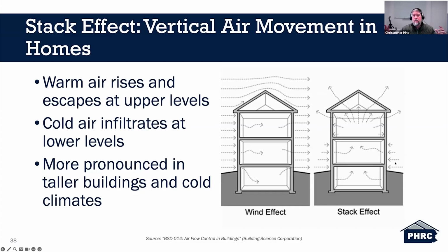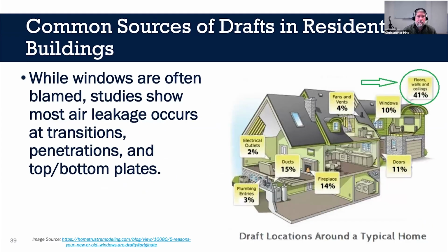Again, because you are creating a depressurization at the bottom due to the pressure at the top, and it's drawing air in through the gaps and cracks at the foundation level or up from the foundation. And if it's an unconditioned basement, then you may have foul smells with it. You could have higher moisture content. There's a whole host of items that can be adverse when looking at the movement of air from outside to in, and through stack effect.